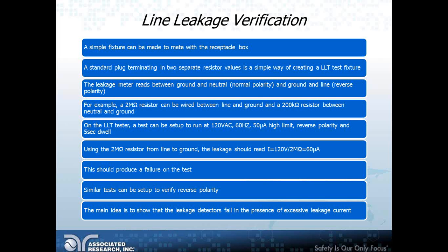Now, while a line leakage tester usually does contain various other relays, the main idea here was to show that the leakage detectors on the instrument fail in the presence of excessive leakage current. The two tests that we just outlined for verifying line leakage testers prove whether a line leakage meter is reading leakage values properly or not.